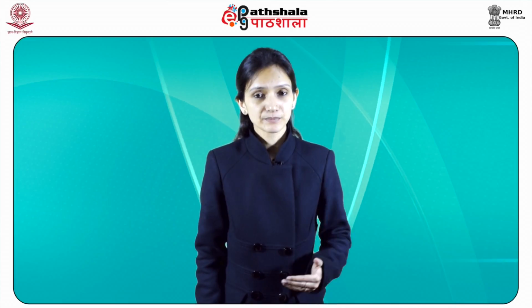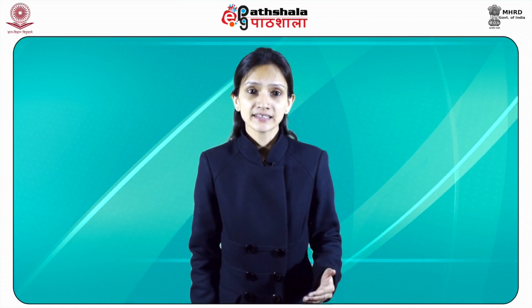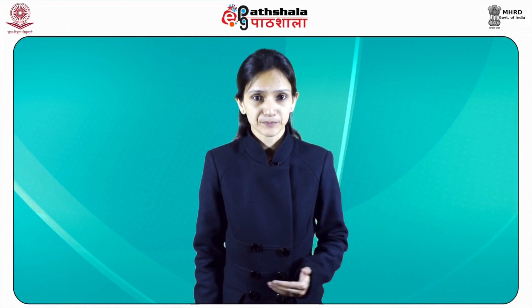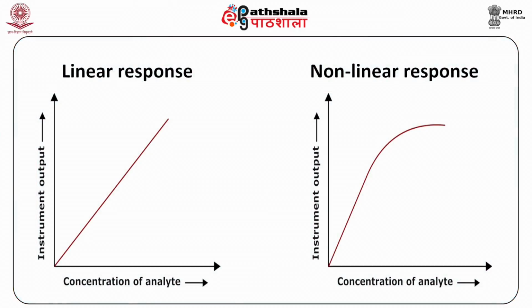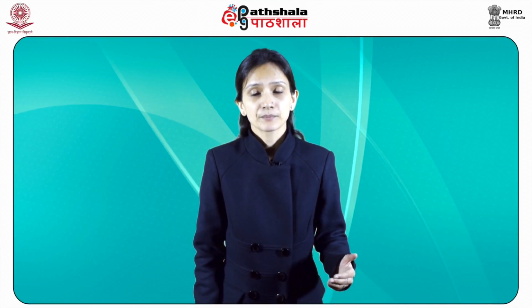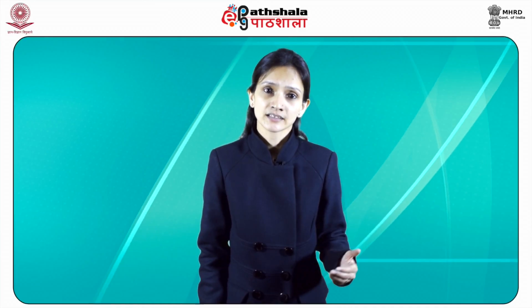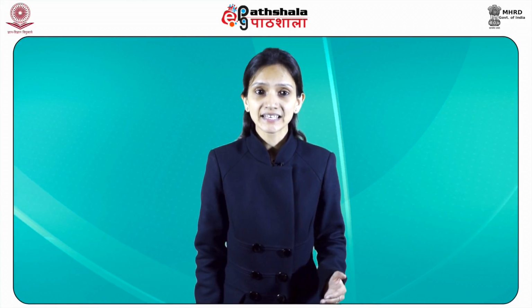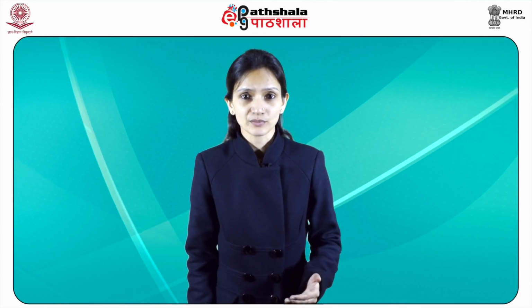It is usually desirable to maximize the sensitivity value unless one wishes to extend the instrument's range of response without diluting the sample. Figure 1 shows a linear response, that is constant sensitivity over the entire range of measured concentrations. The non-linear response in figure 2 indicates a constantly changing value for sensitivity as a function of concentration. Measurements of substance C become less sensitive with increasing concentration. Sensitivity may also be expressed as the concentration of analyte required to cause a given instrument response.